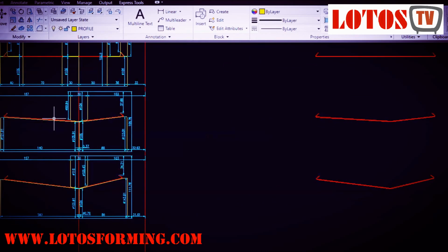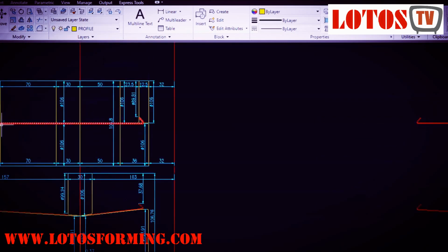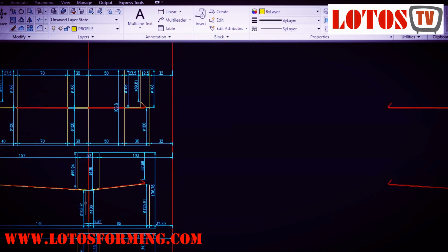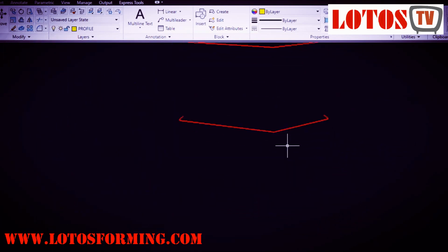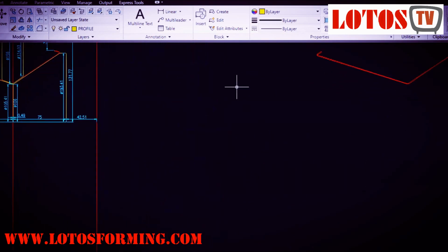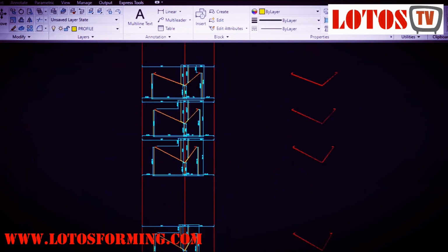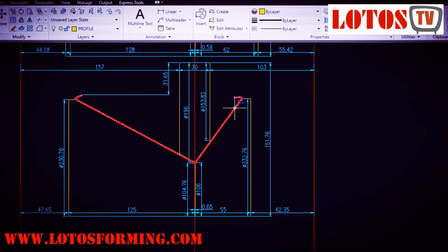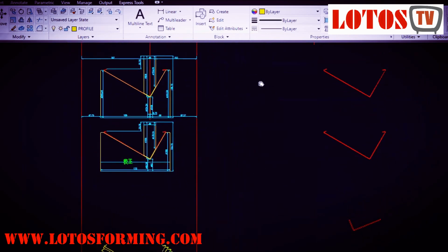Till here is totally flat, up roller and down roller connection. As you can see, it just has 2 side deformation. But from here, we start forming this angle. Okay. We're reaching number 9. You can see these 2 sides didn't touch after the number 3 station, just working on this angle. And we're reaching the final profile here.